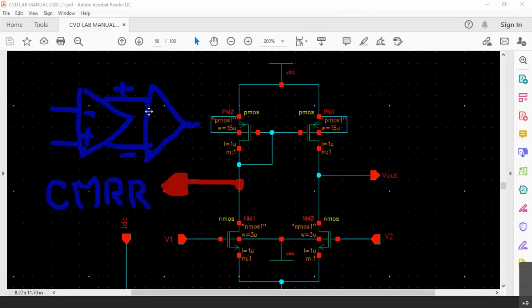Now, later on we can have a single-ended output. We are connecting one dual input, dual output amplifier so as to have minimum noise amplification, so as to have only signal amplification. Later on, we can have a single-ended amplifier at the output. That is why many times amplifiers are multi-stage. They are not single-stage amplifiers. Now that is the advantage of taking both outputs.